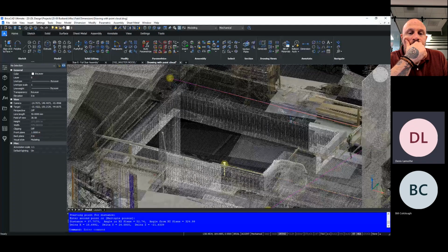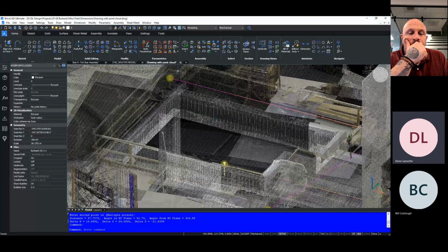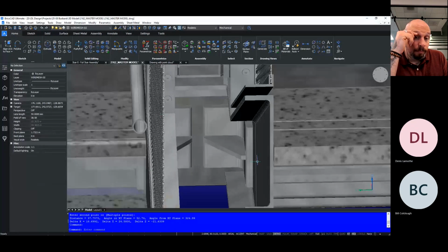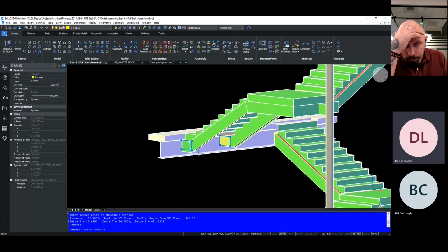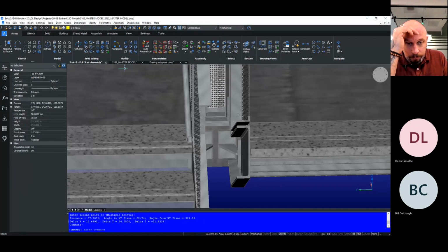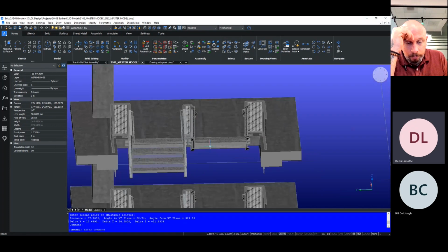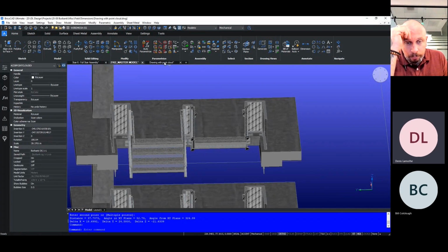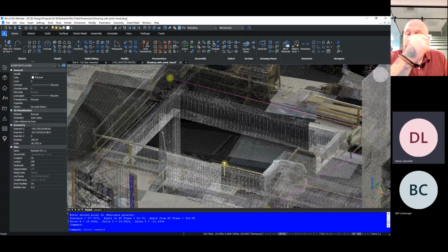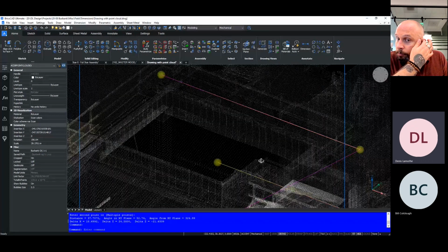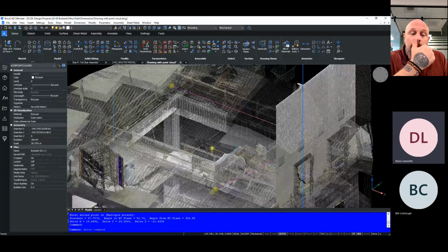I believe at some point it is also the intent that we can insert these point cloud drawings into our models, and then ascertain where the floors are from what we've drawn with the point clouds, and see if there's a bust somewhere. Did we correctly factor in these field dimensions when we modified our stair to suit?